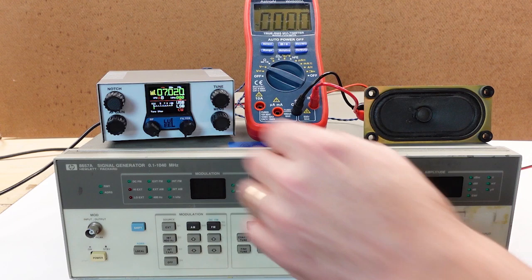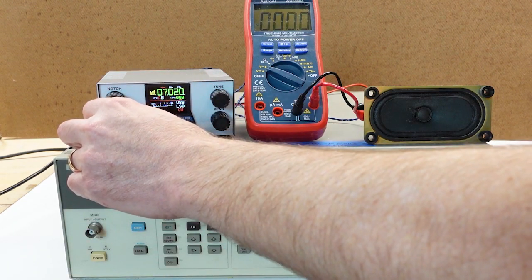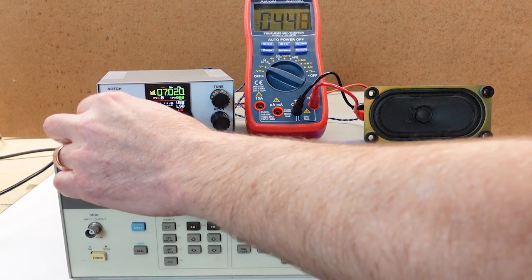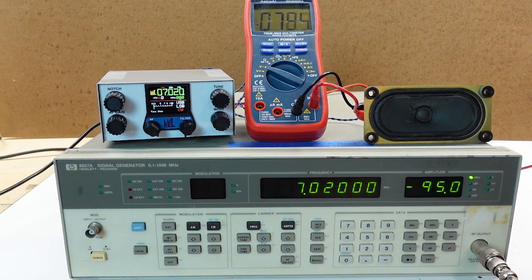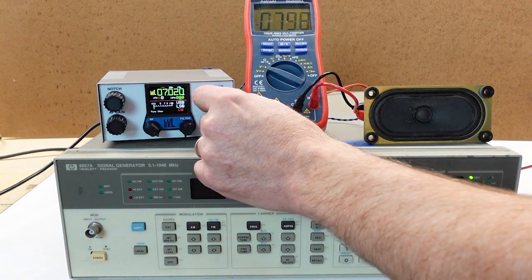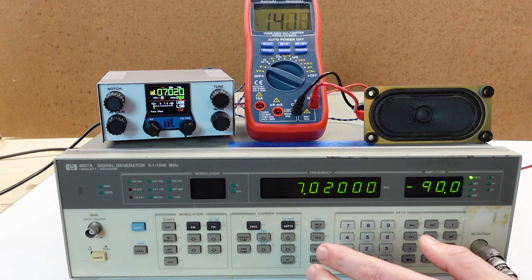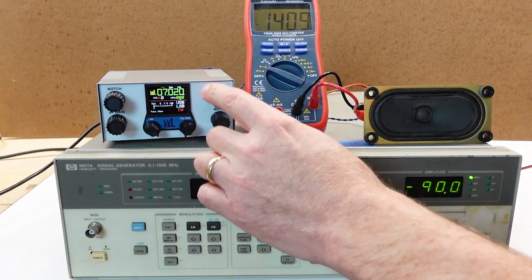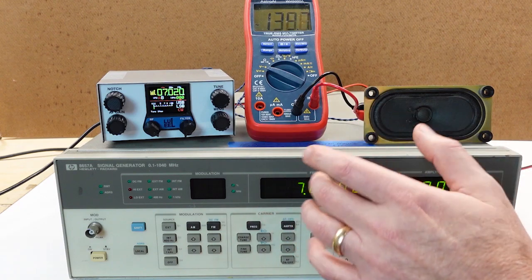Now, when I turn on the receiver here and then turn on the signal generator, we can get a tone coming out. And what I want to do is adjust the frequency slightly until I get a peak here. Because really what I'm looking for is to make sure I have the receiver set to get the maximum amplitude for the IF filter, which is not perfectly symmetrical and has a little ripple in it.